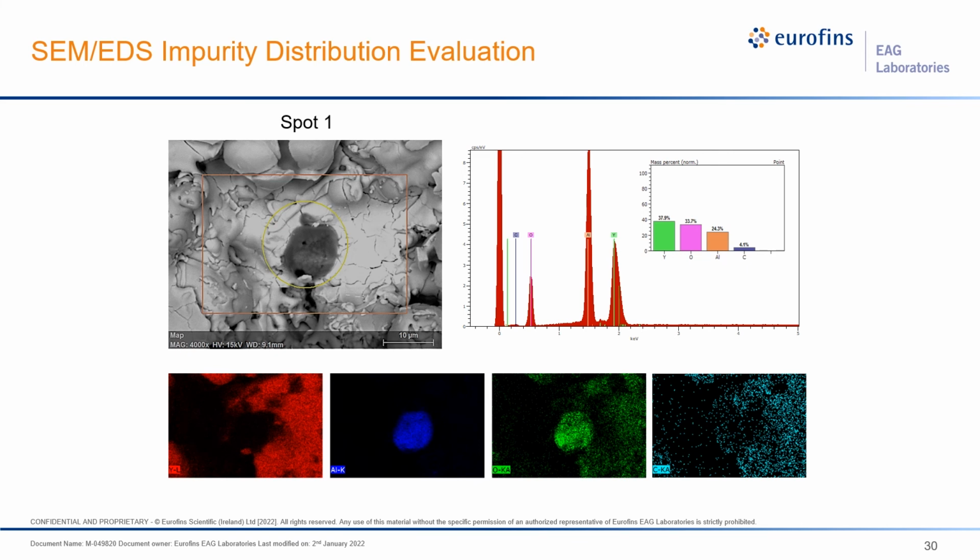Here I give you an example. We're using SEM EDS to look at the surface. We see those inclusions, which are actually aluminum oxide. So if you hit it, you have it. Otherwise, it is not there. So sample heterogeneity is often one of the major sources contributing to measurement variations, or the major source of lower precision.